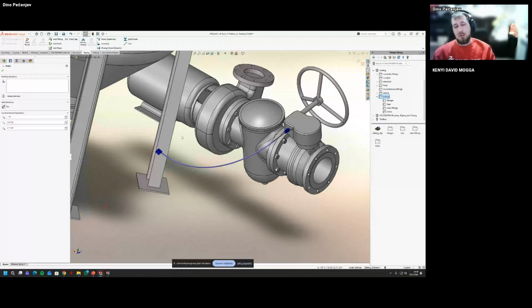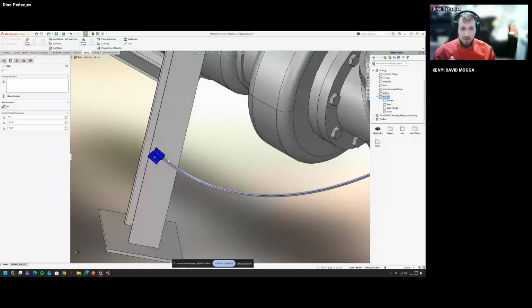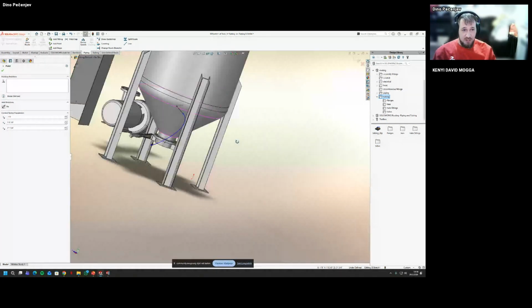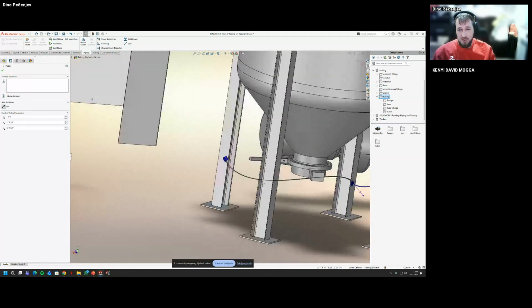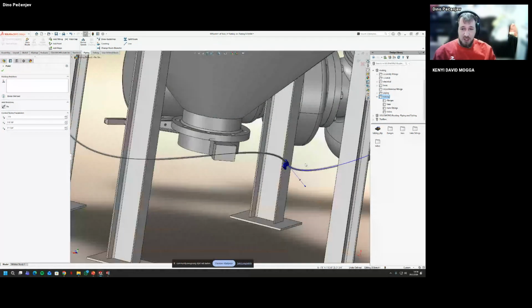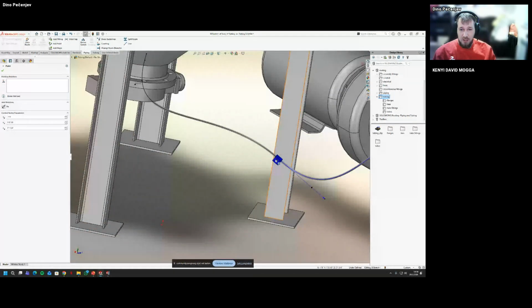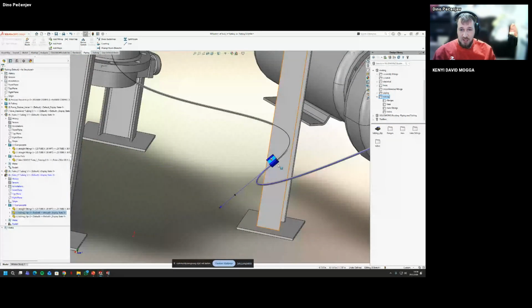And what it does when you use the clips, this also propagates, for example, to electrical routing. It will automatically route to the other side. So here I can just set, okay, I need another clip. It will route it. And this is all right. I can manipulate the sketch. But let's say I want to use it like this.